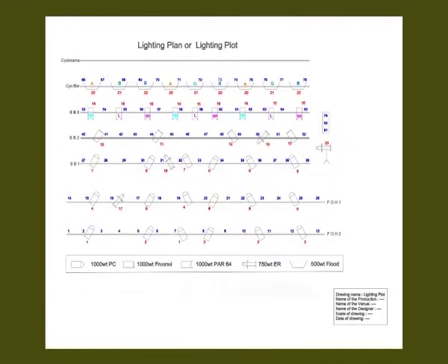You will see that all dimmers are not in use, which means you still have a chance to hang more equipment. Sometimes it happens that after the grand rehearsal, you may feel the need to add 1 or 2 special lights. For that, you need extra dimmers, and there they will help you. You will also find that for some fixtures, the channel number is the same, which means that they are grouped together. For grouping, you need the dimmer number, which you will learn when I discuss the patching sheet.